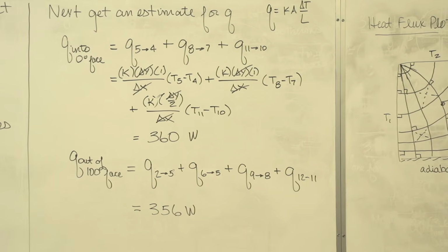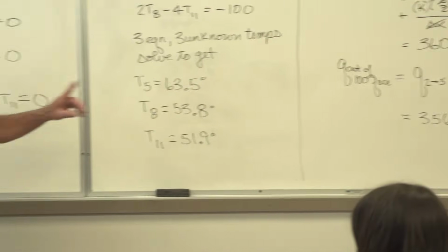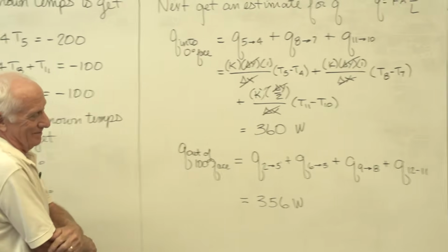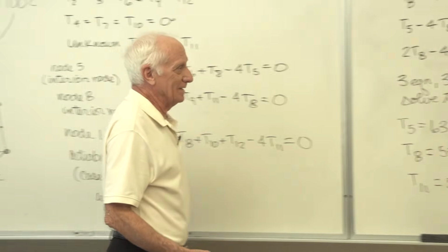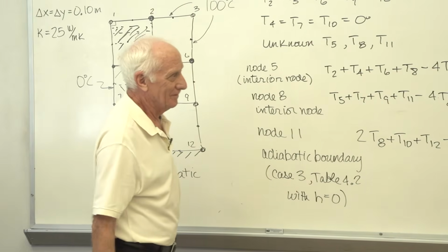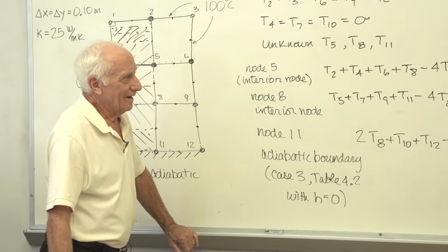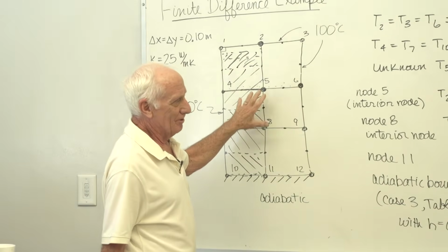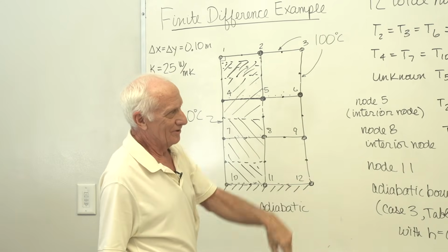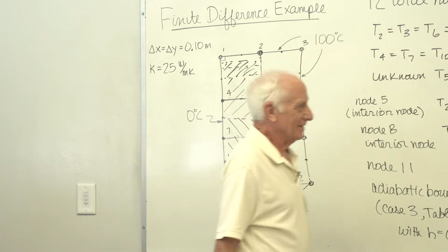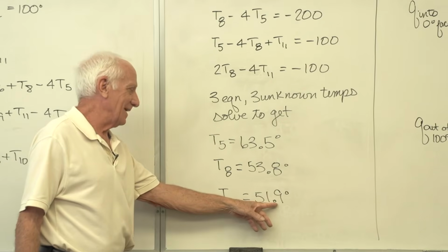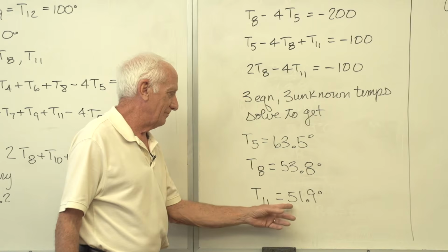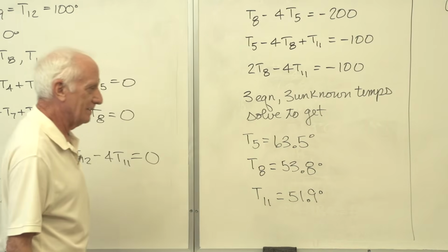The finer your grid size, the closer they're going to agree. But again, at the expense of what? Computing time. Is it worth it? That's your call. Okay. The finer you make the grid size, the more accurate your temperatures are, and the closer Q is to the actual Q. These guys here, that 9 means nothing. It might be anywhere from 50 to 51 to 53, that temperature.